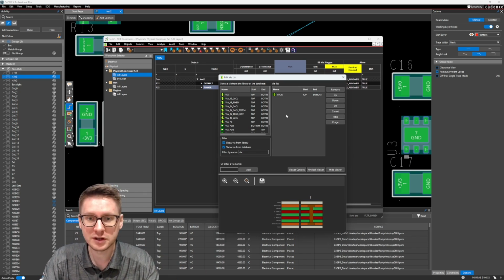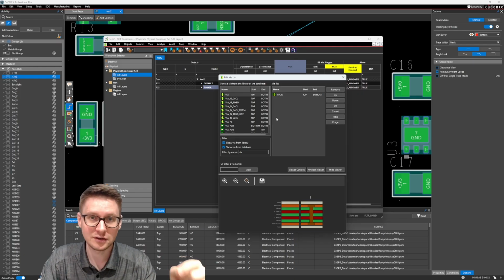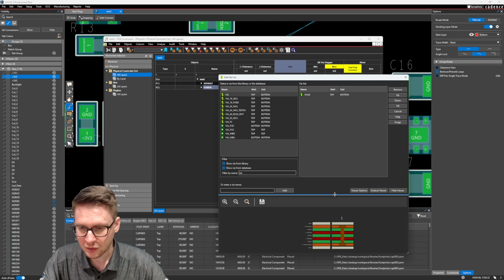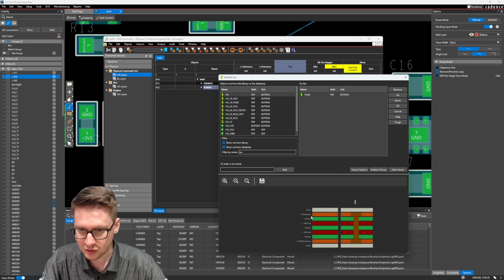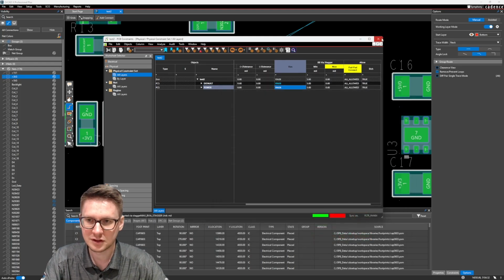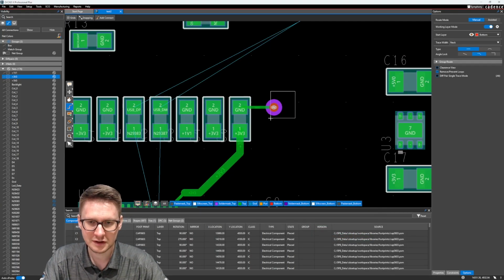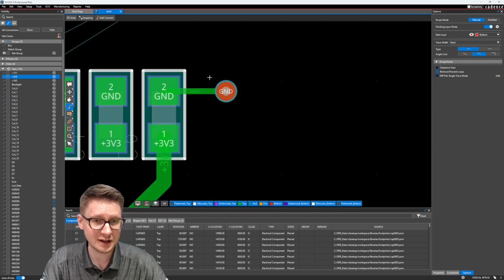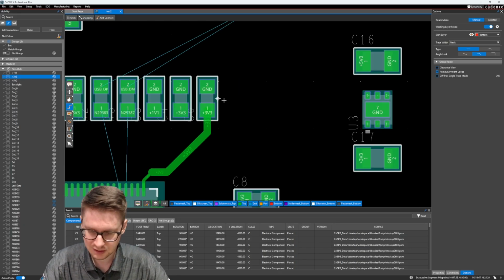Or even if you're using micro vias, you can have multiple vias here. One via being, for example, from your top layer to the second layer, and to the third layer, a separate via. And you get this nice preview at the bottom here, which will show you this via 26 goes from my top conductor layer to the bottom conductor layer. So click OK. I have via 26 defined. And now if I delete this and start routing again, this is my via 26. I believe the only difference here really is that it has a slightly smaller solder mask expansion around the via. Otherwise, nothing too crazy.